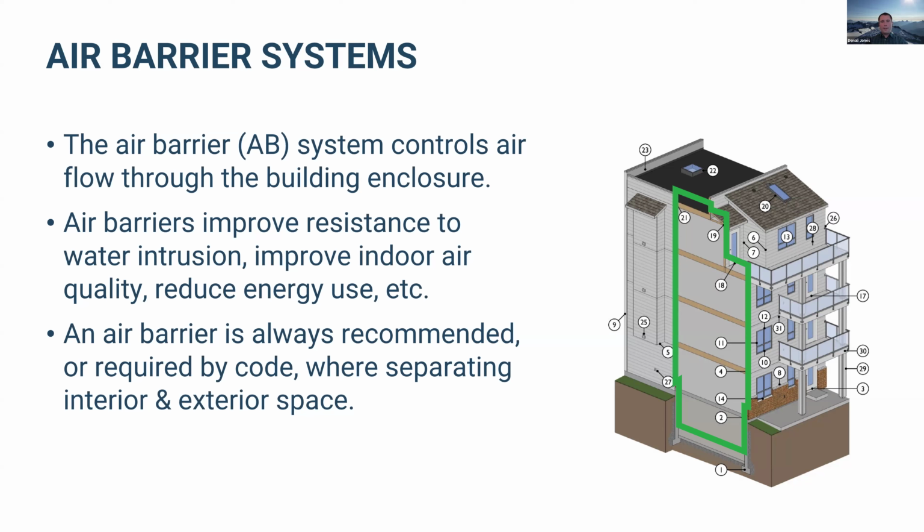If you're like me and you just stare at buildings in construction all the time, I like to spot rainscreen assemblies out in the wild when things are under construction. I don't know if anyone else does this too, but I like to get out there and see if I can identify where the actual drainage layer is, how it's going to dry out, whether there is enough of a cavity for airflow, and whether they are blocking it anywhere. This is a fun activity I like to do when I'm out around a new city or even in my own city.